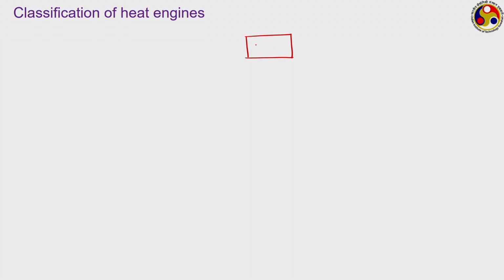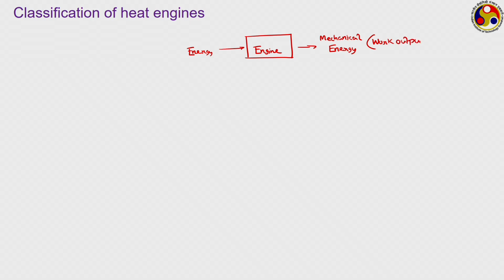device. That is, if we just represent in a block sense, an engine always corresponds to receiving energy of a certain form from some source and converting that to another form of energy, and generally the term engine is primarily associated with when the output side energy is in mechanical form, which can be a change in kinetic energy or potential energy or maybe in the form of some thrust or shaft movement, thereby giving you, more commonly, what we can call work output.